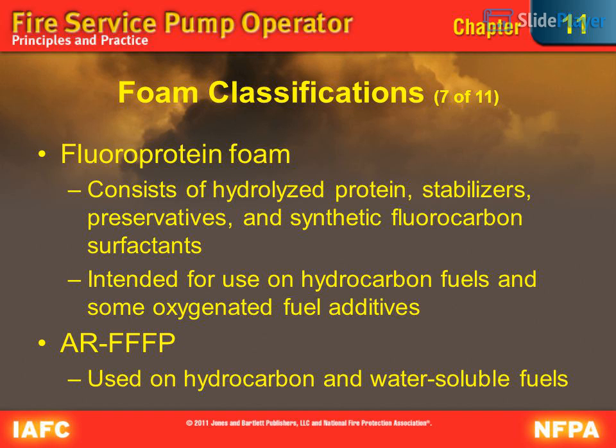Foam classifications, 7 of 11. Fluoroprotein foam. Consists of hydrolyzed protein, stabilizers, preservatives, and synthetic fluorocarbon surfactants. Intended for use on hydrocarbon fuels and some oxygenated fuel additives.